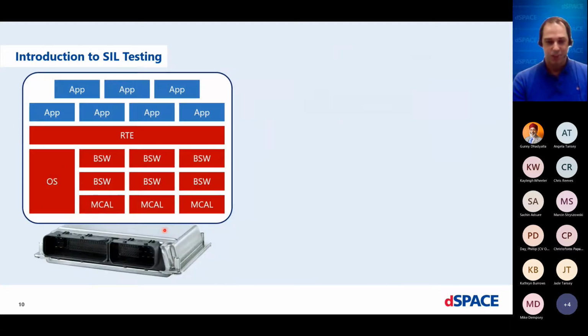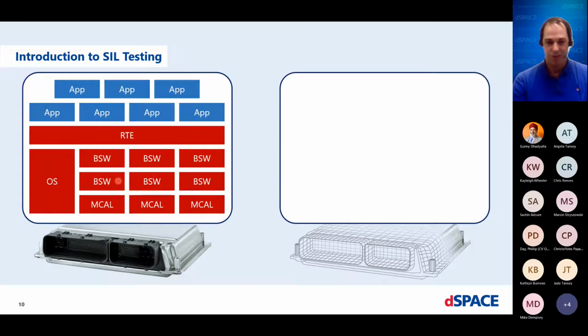Yeah, what does an ECU look like normally? If you come from an AUTOSAR background, you normally have your different software applications running on the ECUs, and you have a runtime environment, and you have your basic software, and then you have all your drivers and operating system running on the ECU. If you want to virtualize that, you need somehow to transfer this software into a virtual environment.